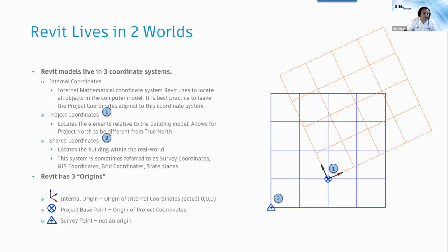This is what sets up your project north, east, west. By default, all of your views in Revit are set up this way, and there's a reason for that. Out of the box, this is what's important, because until you've talked to somebody, you have no idea where your building is going. I don't care if you've looked at a civil plan and you think you know where it goes. You can get close, and you might be able to get the X and the Y down, but until you get a civil engineer involved, the Z is really tricky. And so it has to be a collaborative effort.